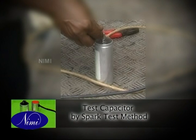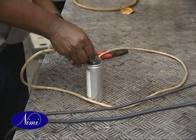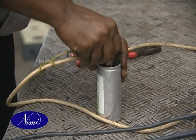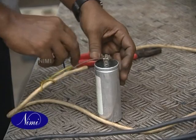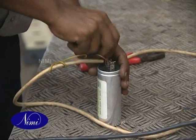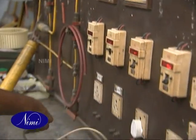Test capacitor by spark test method. Prepare the test board. Connect probe A to capacitor terminal 1. Connect probe B to the other terminal. Connect the cord wire to the power source.